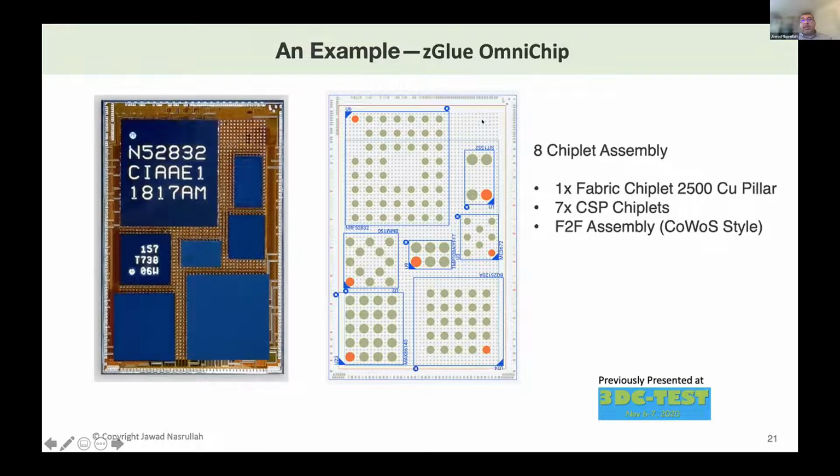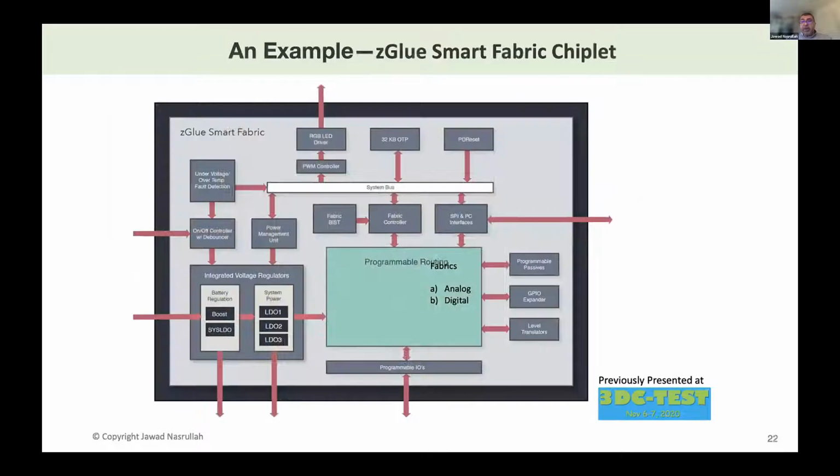That bed of nails, in the fine pitch resolution that you are seeing, is primarily designed for test. It's designed for test to make sure that there are no defects in terms of opens and shorts. But more than that, if we need redundancy, we have that. In a way, if you look at high bandwidth memory, you would see the design is kind of similar, in that they're putting diversity of multiple bumps for one signal at times, right? So it was along the same concept. And you start digging into it.